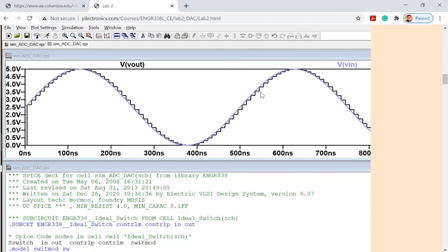So keep in mind, remember you used a very sharp edge for the input for the RC circuit yesterday. Remember? So the input is a really steep edge. The time delay is pretty much 0. Like you can set it up as 1 picosecond. However, you are going to get something like this. So you can calculate the time delay. Is that smoother compared to the sharp edge? It is, right? Because it takes time to charge up the capacitor. So you can imagine if you have a low pass filter, all these sharp angles, the sharp steps will be smoothed out. Will look smoother, right? So that's why it happens.